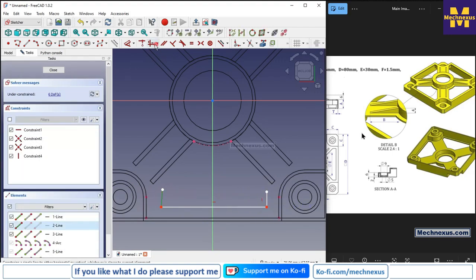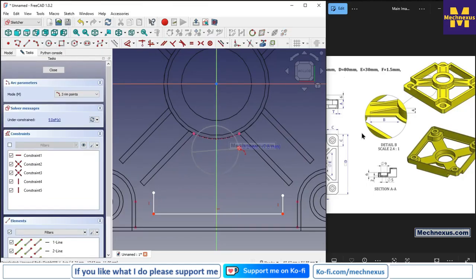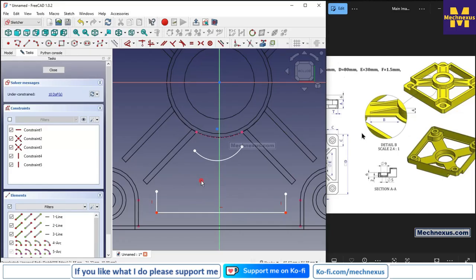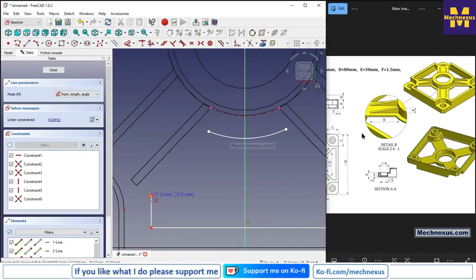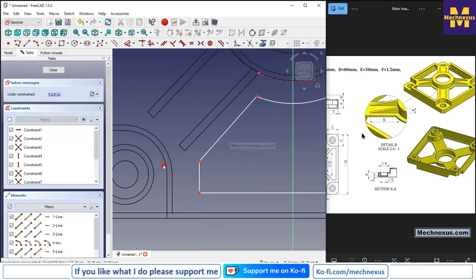Now select it and make it vertical, and here I will create a 3-point arc, and its center will be the coincidence, add a coincidence relation. And now select the line tool. Now select this and this, and let's add the dimensions.